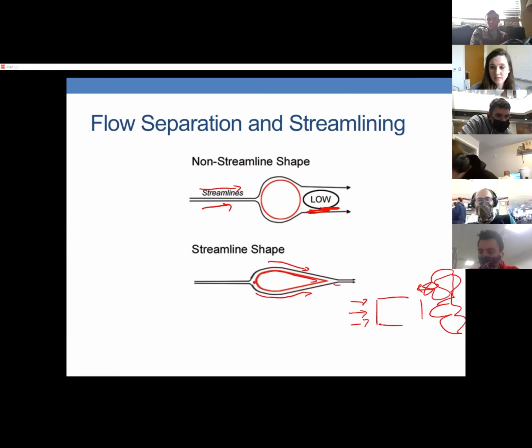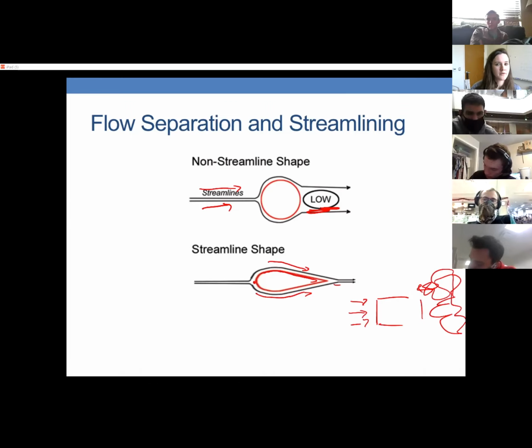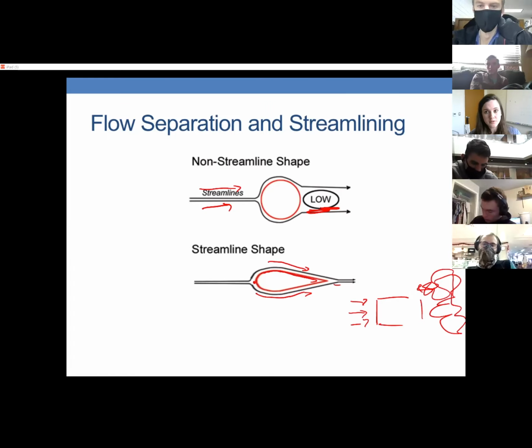Okay. All right, so 91% of you say no, and you are right, because in very, very low Reynolds number flow, we don't get this flow separation anyway, because that really slow viscous flow is just going to wrap around the object. And so streamlining it would likely not decrease your drag very much. Instead, you should focus on making it smoother, for example, so there's less friction. That is what you would do if you were trying to minimize drag in a very, very low Reynolds number flow.